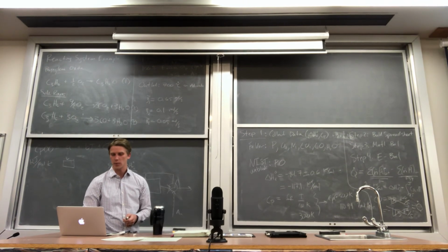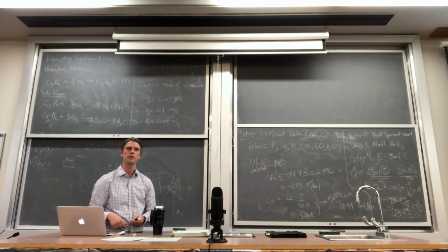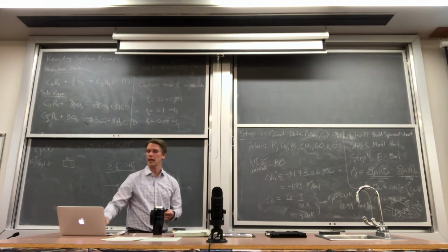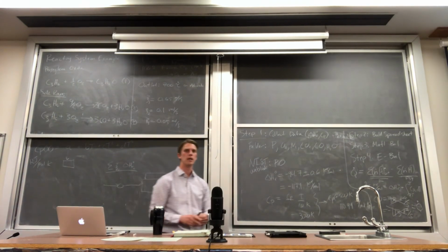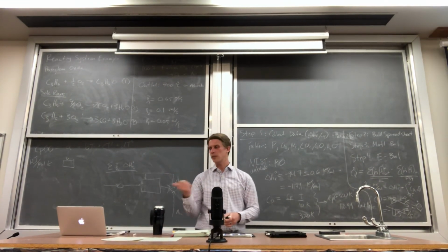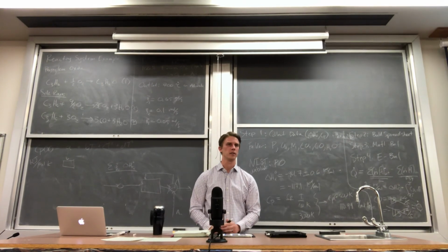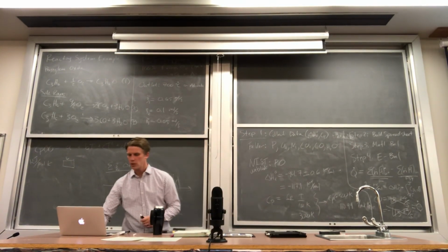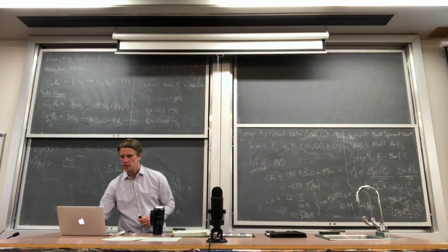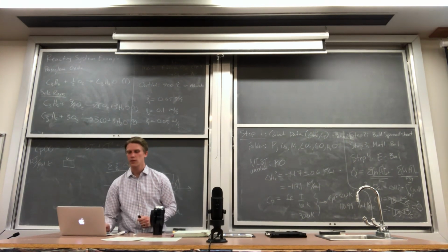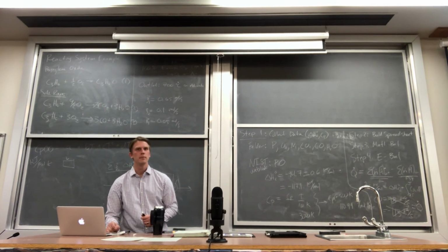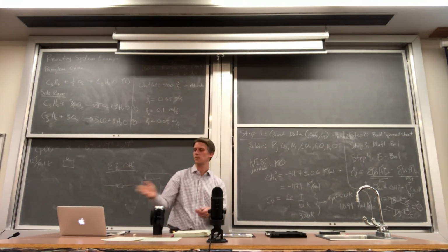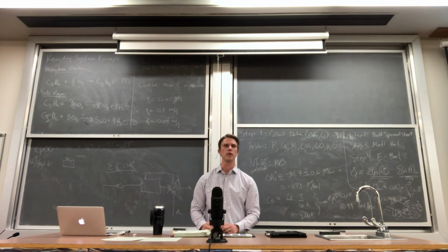The only difference is that we would just have to change all of these stoichiometric coefficients to 0 because there would be no reaction, and we would just not consider the heats of formation. But you could, to some extent, use the same spreadsheet to do a non-reacting system as well. Or if you wanted to, you could go through and manually change these terms here and delete that heat of formation. Does that make sense? So for the non-reacting system, if there are no phase changes, then yeah, you could set up your whole calculation just as trivially as this one here.